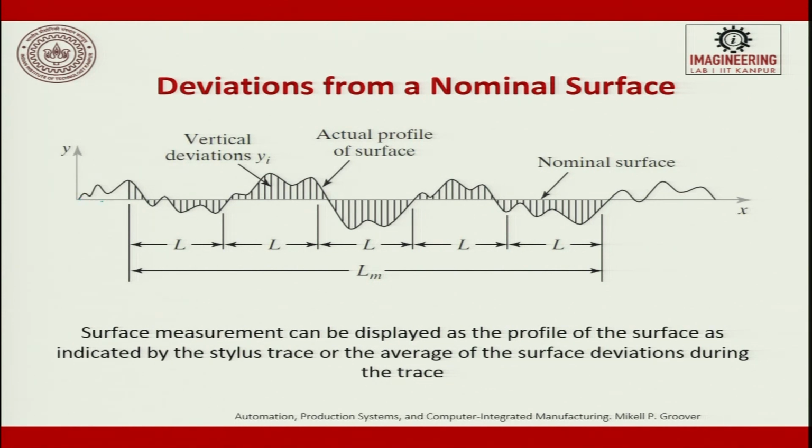The stylus is scribed over a surface. So, you will have several undulations which are getting formed, and these undulations will be divided into several small segments, and what they do is they try to find out the area above the line and the area below the line is uniform. Okay. So, this is the place where the stylus starts scribing, and from here onwards we start the measuring distance. So, this is the measuring sample length.